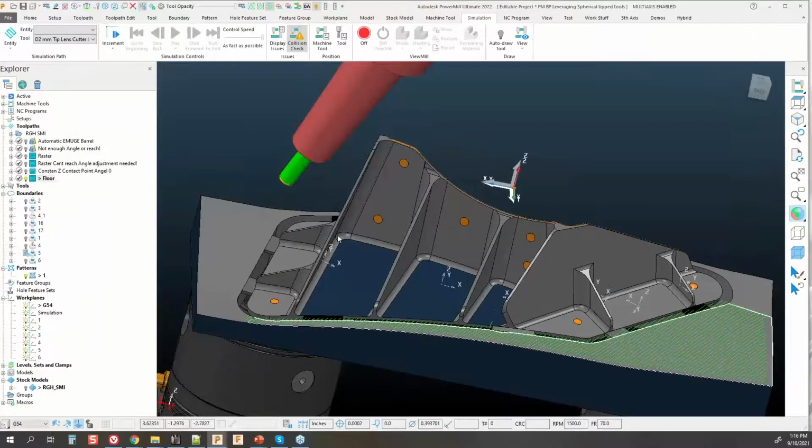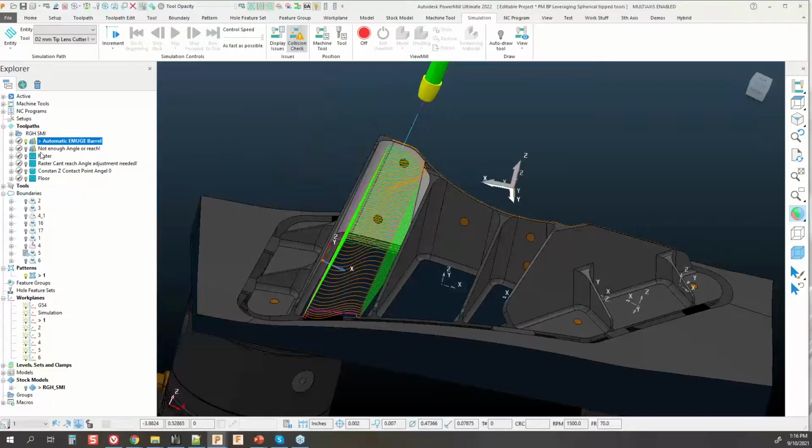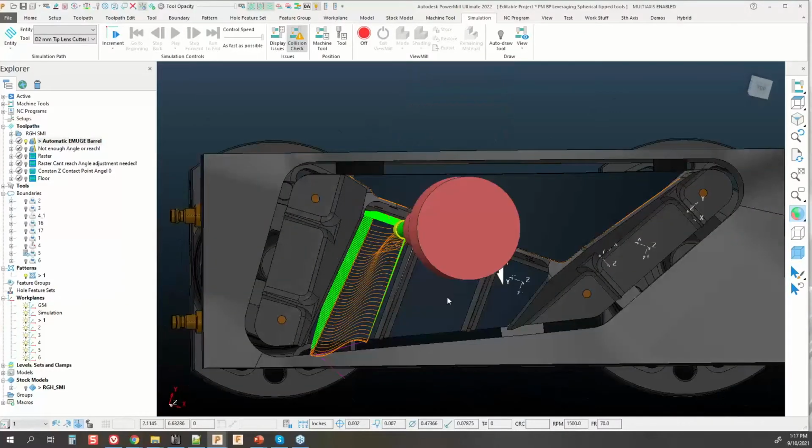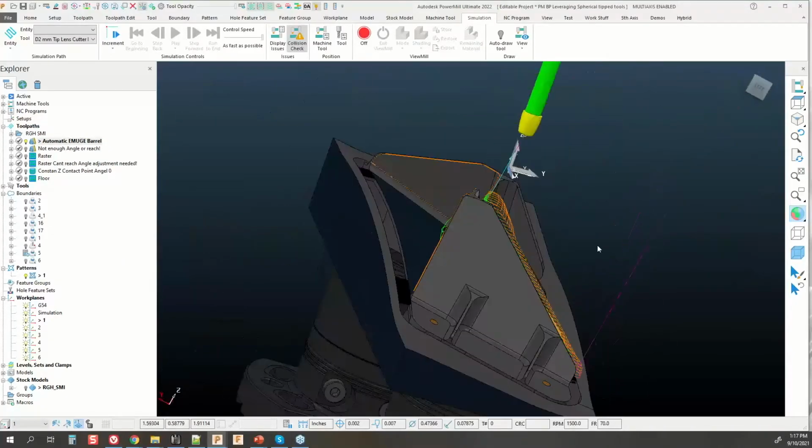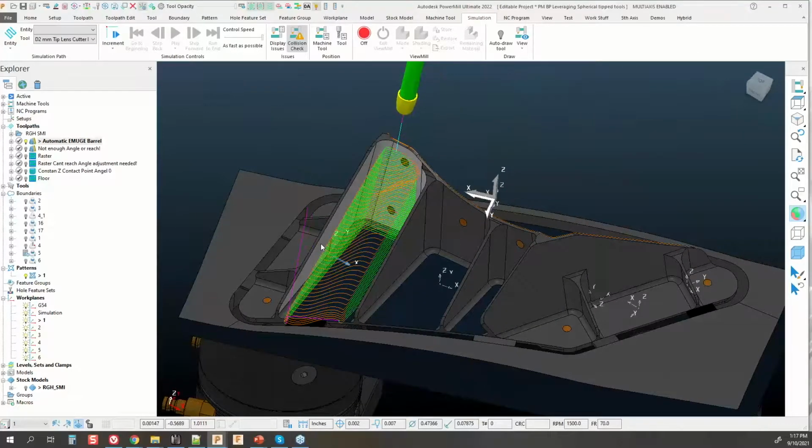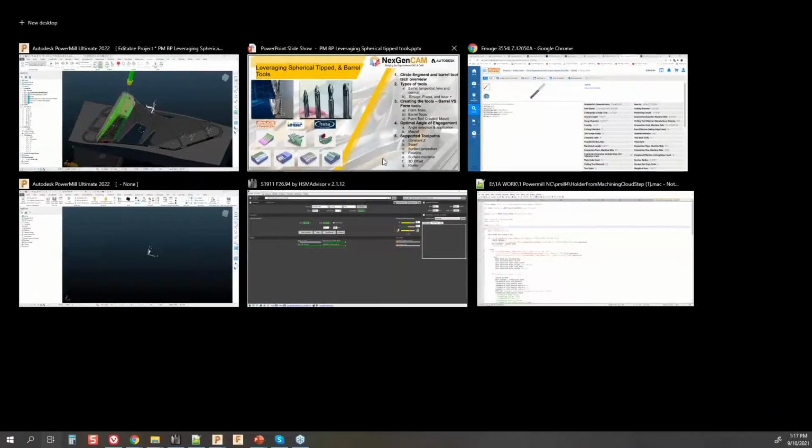So once we get into our toolpaths here for today, I'll go through each one of these, including raster, including Swarf. Starting out with Swarf, then we'll go into raster and Constant Z as we go through the toolpaths, and show right out of the get-go what you're looking at when you start using these toolpaths, and what's going to fail and what's going to succeed, because there's a lot to this part and many different angles, many different undercut regions that we're going to try to get to. Let's go back to our cutters real quick.